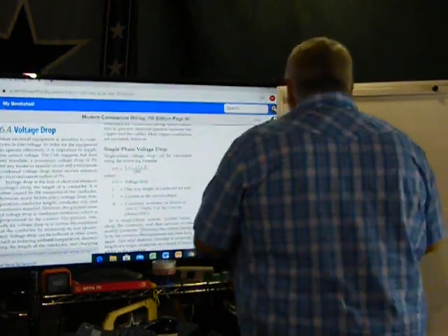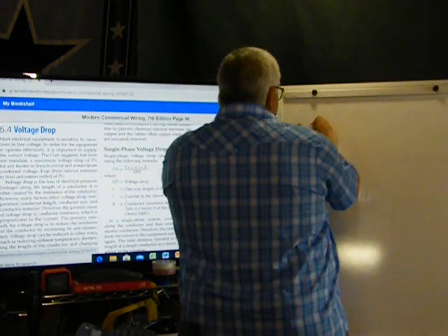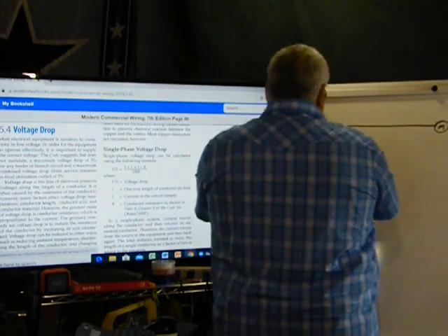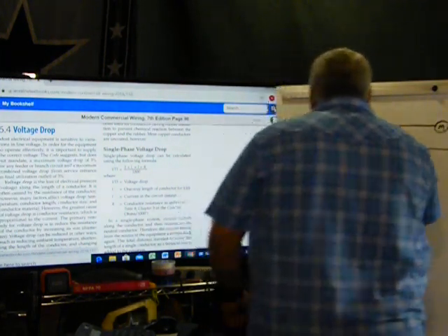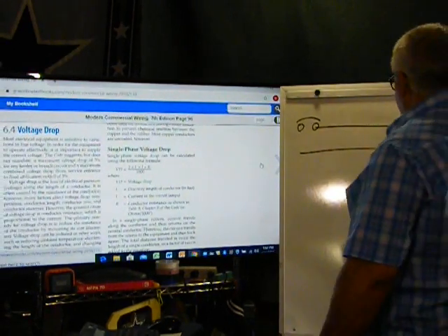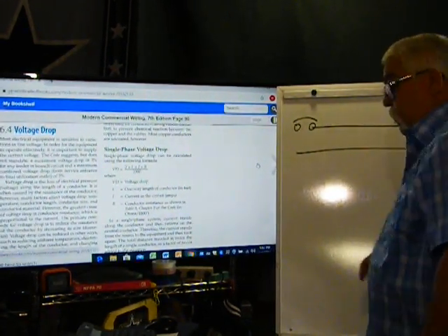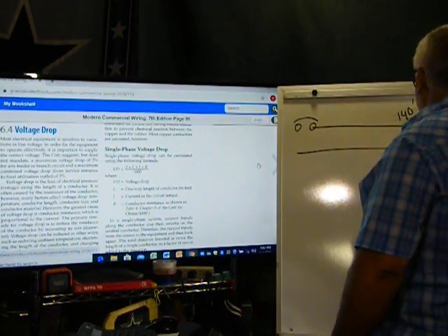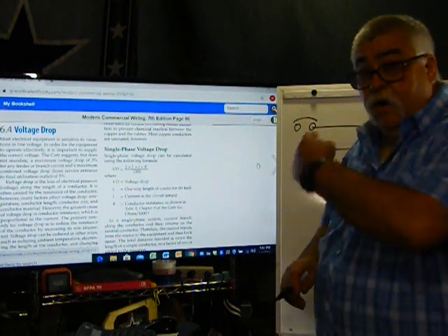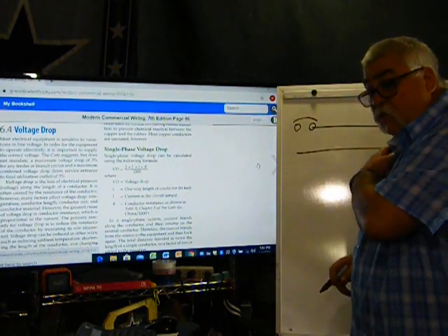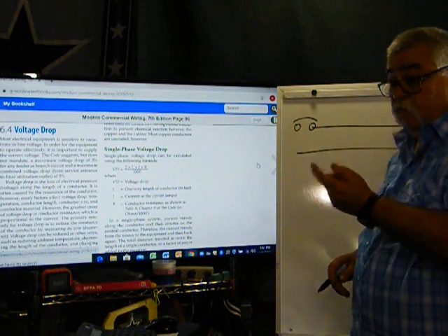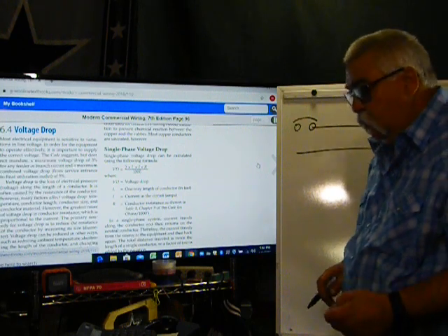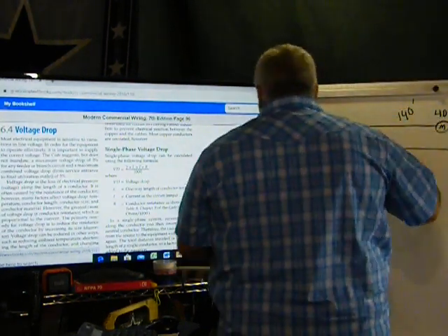At the number 8 wire, let's say I had a circuit that went out, and it's 140 feet away. Okay, it's 140 feet away. Let's say this is 40 amps. I need a wire that can carry 40 amps. Obviously, I can't use a number 8, because with the temperature alone, it doesn't help. It's at 37.6, I think it was. 37.6.